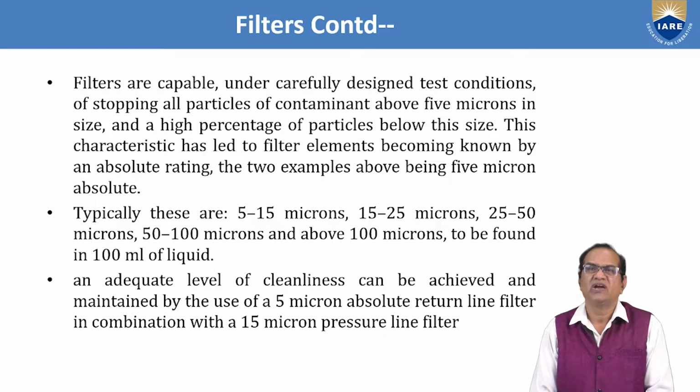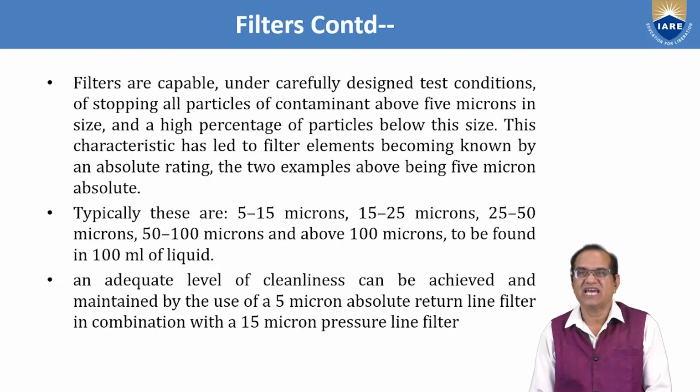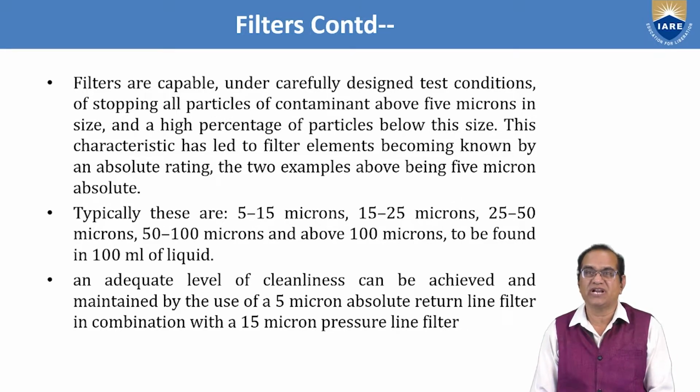Now filters are capable, under careful design test conditions, of stopping all particles of contaminant above 5 microns in size and a high percentage of particles below this size. These characteristics have led to filter elements becoming known by an absolute rating.